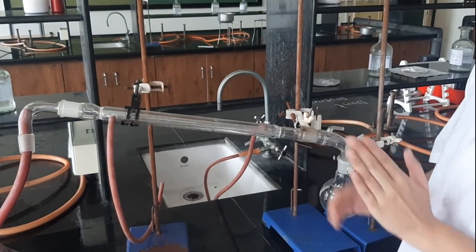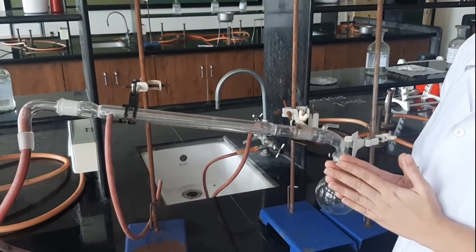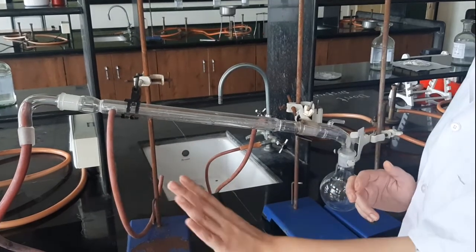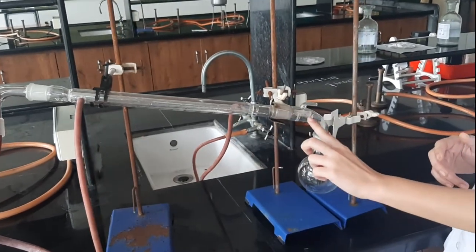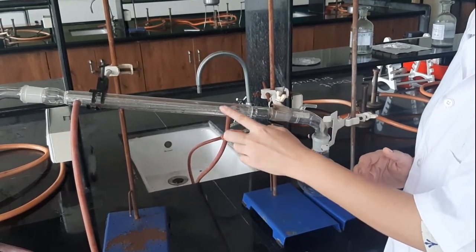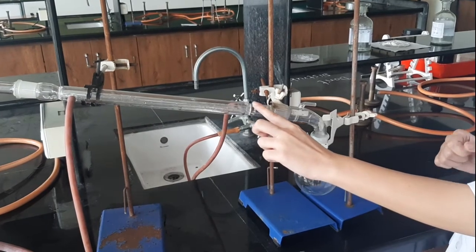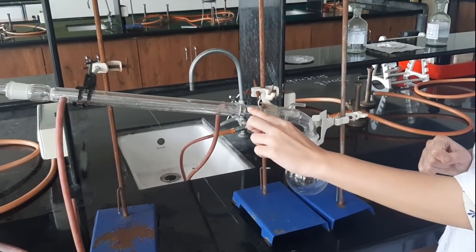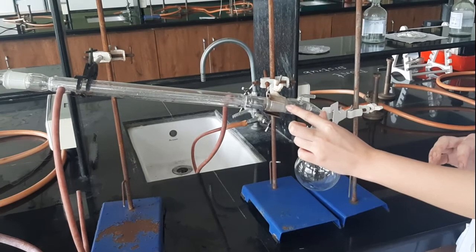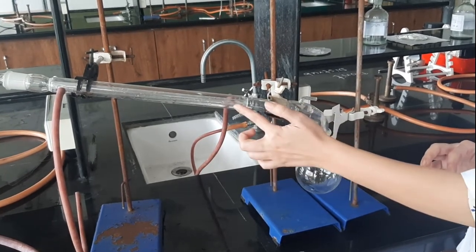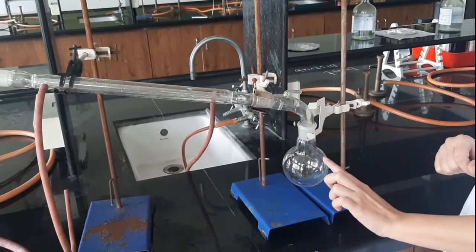Keep in mind we have to measure the volume as well as the temperature of the water which is flowing from the outlet of this condenser. That water is important and we will collect it using a drum. After the steam passes through this condenser, it will get cooled because of the heat transfer process between the hot fluid and the cold fluid. As it moves along this length, the steam will get condensed and form liquid water, and that liquid water will be collected in this receiver with the help of this adapter. The condenser is connected to the adapter and that adapter is connected to the receiver. So all the water will be collected.